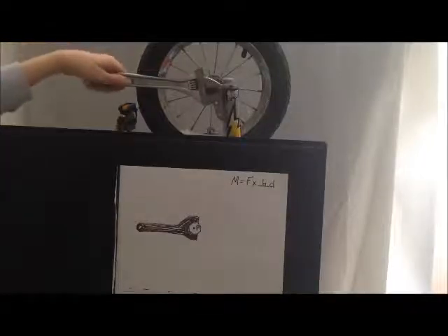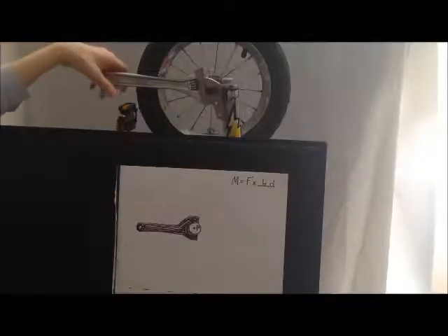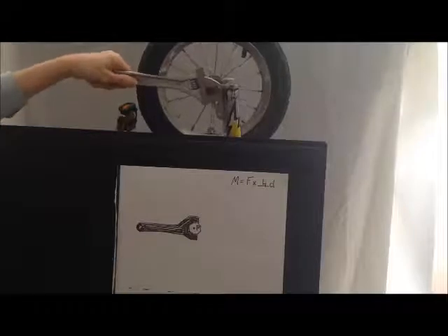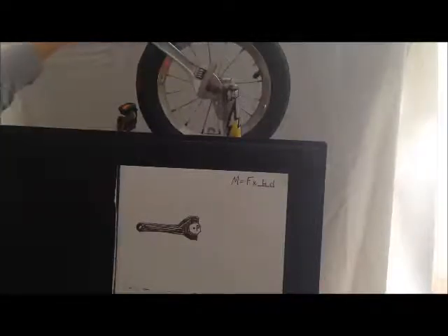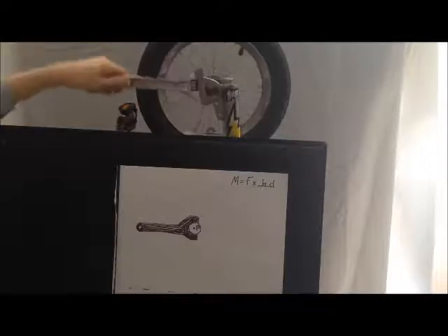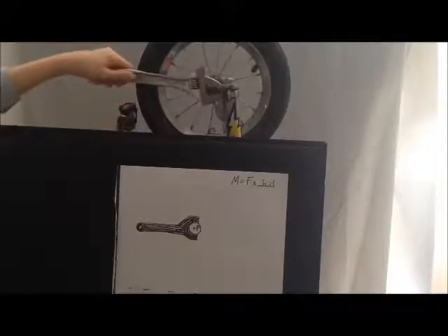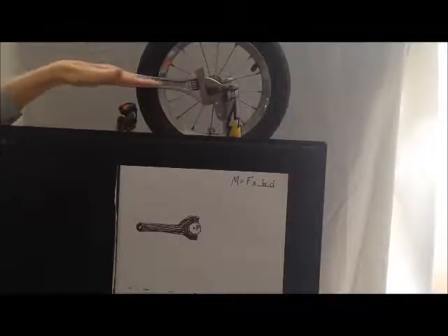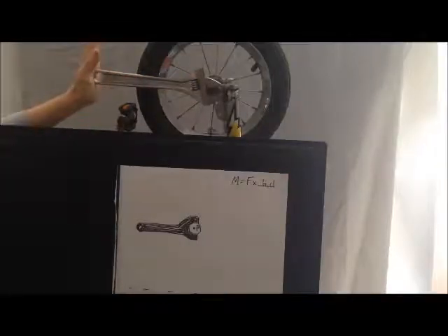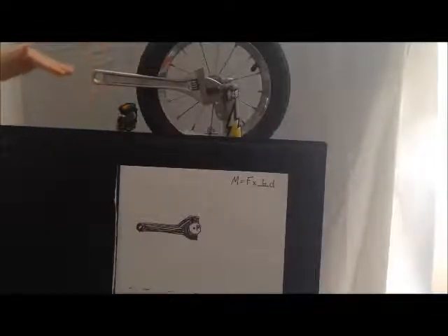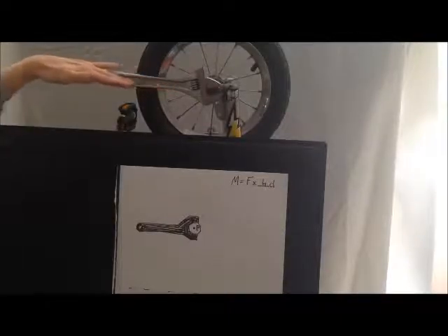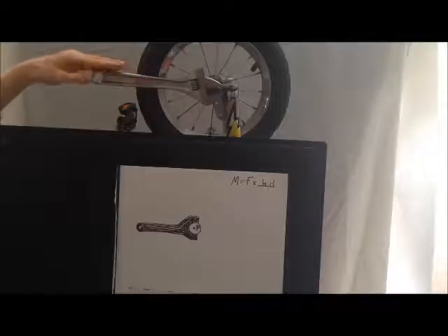You intuitively know this because when you use a spanner, it doesn't matter which angle you put it at, you always press perpendicular down to the spanner. If you're up here, you're still pressing this way, perpendicular. And if you're down here, you press this way, perpendicular. If you press along the line of the moment arm, nothing happens as far as twisting goes. That is, there is no moment. You can see, because your force is along this line, there is no perpendicular distance. So it's a force times 0, which is nothing.